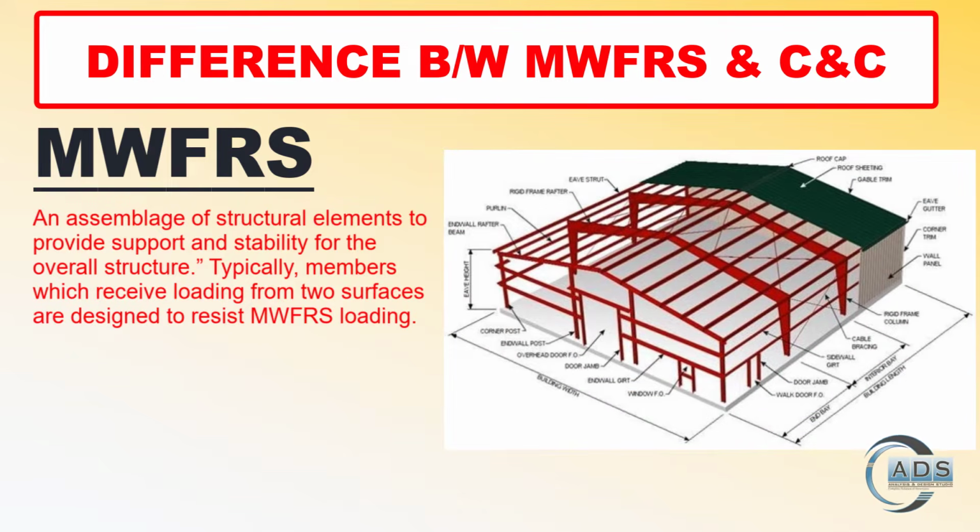Let's say we have a steel moment resisting frame building with metal roof and wall panels as shown in the picture. We would design the moment frames and spread footings at the base of the frames to resist MWFRS loading from the lateral wind pressure on the wall panels and positive or negative wind pressures on